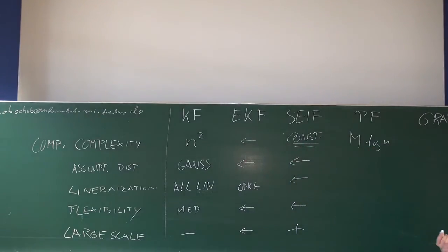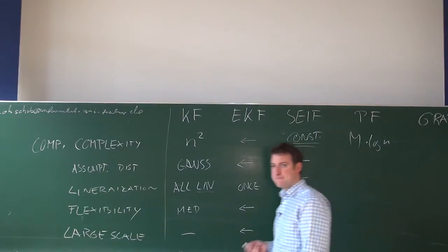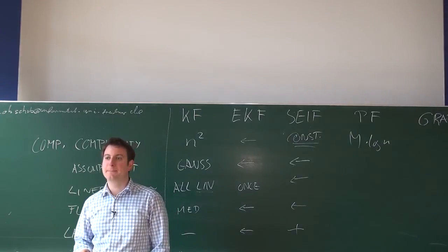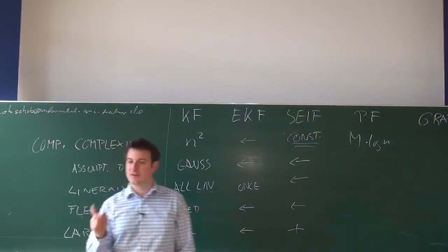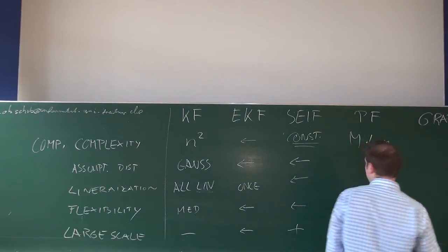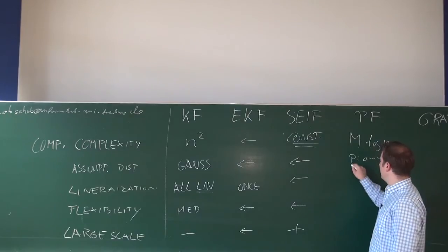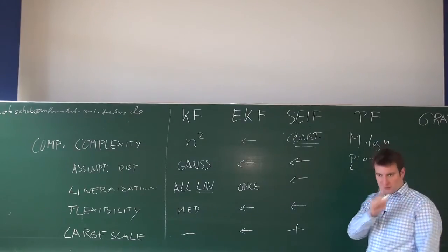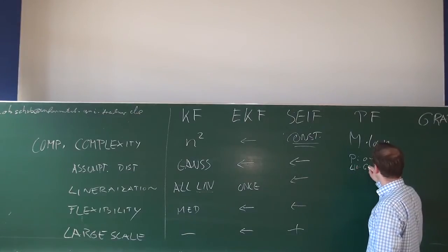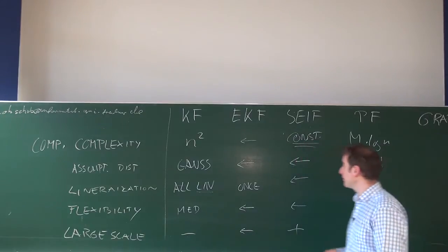What are the assumptions about the underlying distribution? Exactly, I don't make any assumption unless that I can represent it with particles. For the pose, any. For the landmark given the poses, I assume it to be Gaussian, at least for FastSLAM.